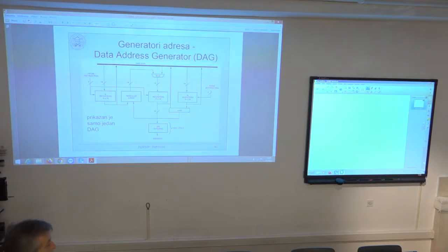And to do this on normal CPU or on some microcontroller, to do this bit reversal, you would have to perform, I don't know, 16 shift operations or rotate operations just to get this proper value mirrored, the address mirrored in the register. And this mirroring is done in hardware.